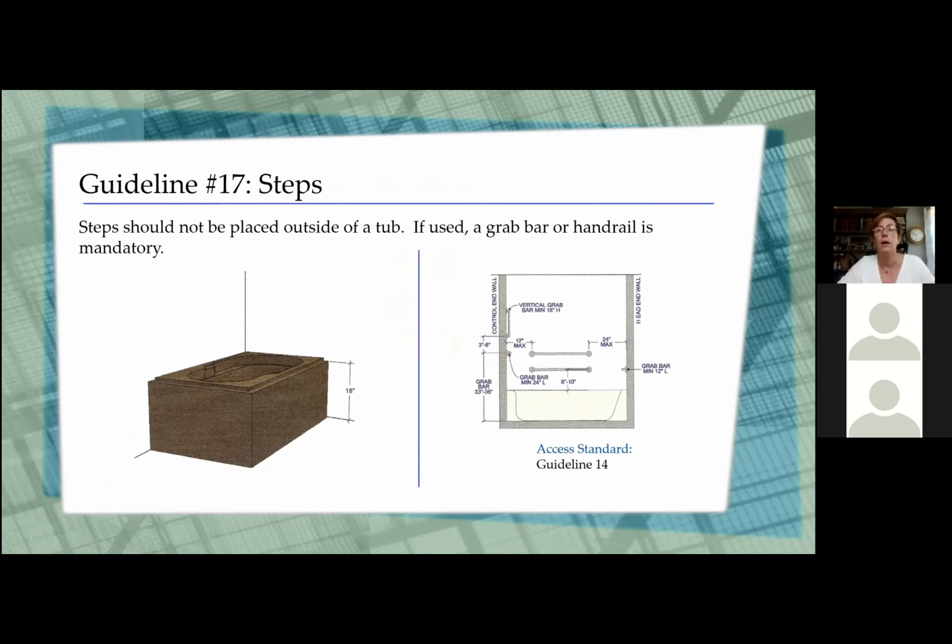A lot of times they say that if you're going to use a step, use a grab bar, but the challenge I would still pose is that if you're standing on the tub deck trying to get into the tub, you're stepping down at least 20 inches into that, and the risk of hurting yourself is really high. Access standards, they're again giving you where those grab bars should be. If you're going to use a step, don't do it.